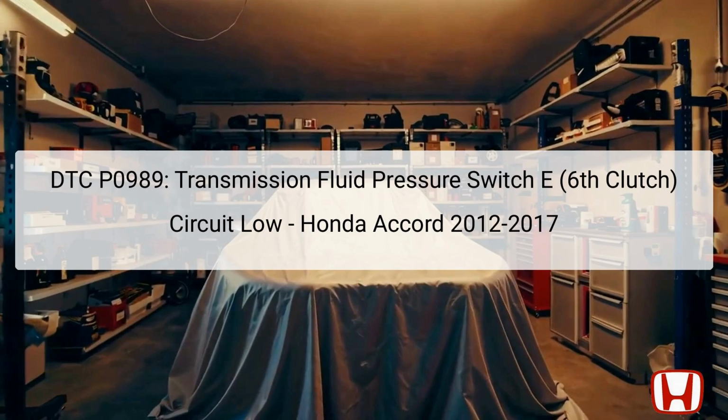DTC P0989 is a diagnostic trouble code indicating a low circuit condition in the transmission fluid pressure switch E, specifically pertaining to the 6th clutch. This component plays a critical role in the operation of the transmission. It is responsible for monitoring hydraulic pressure in the system and is integral to the smooth shifting into the 6th gear. When fluid pressure is satisfactory, this switch activates, signaling the powertrain control module, PCM, to manage gear shifting.